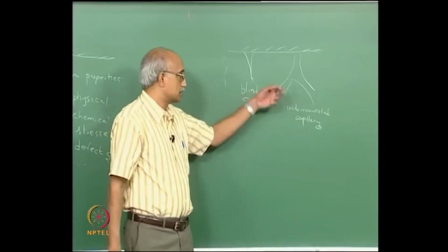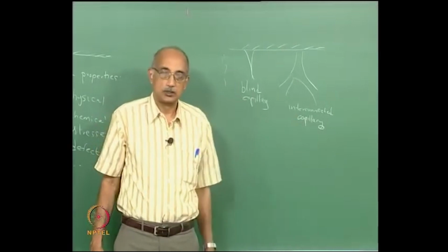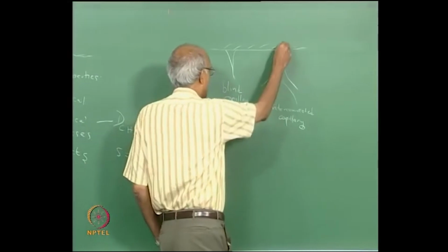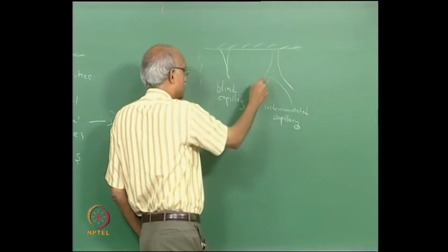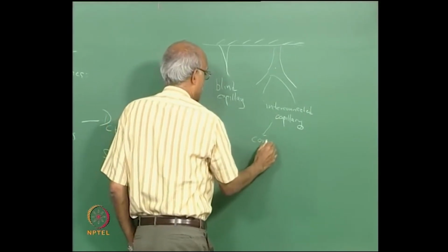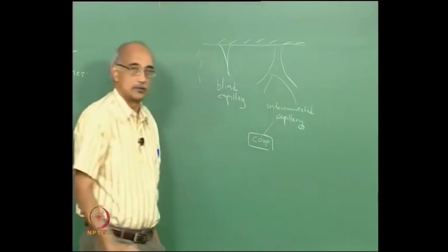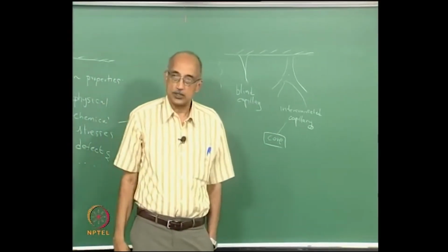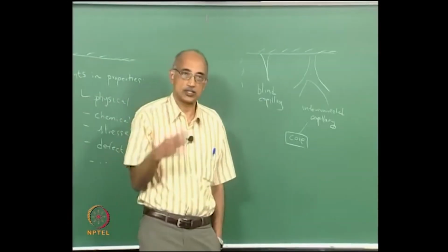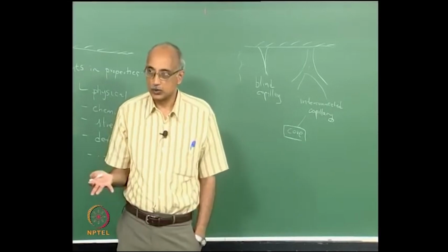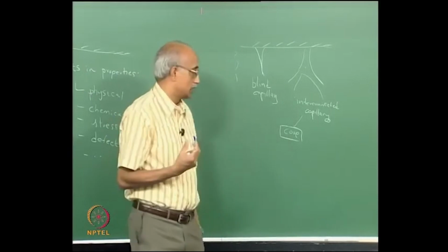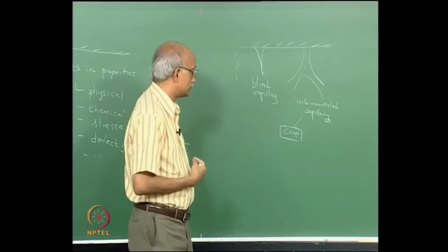Now when this happens, the propagation of the liquid through the particle will be much more extensive, and it can get transported not only at its local area of entry, but throughout the surface, and there is a possibility that this can actually extend all the way to the core of the particle. So depending on what you are trying to achieve, you can either try and minimize these capillaries or try and maximize the capillaries, depending on how extensive an interaction you are looking for between the surrounding fluid and the particle that is suspended in this fluid.